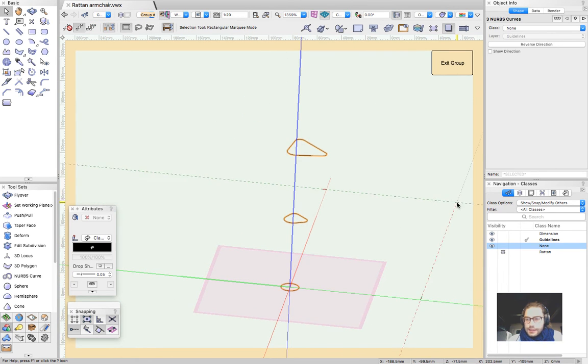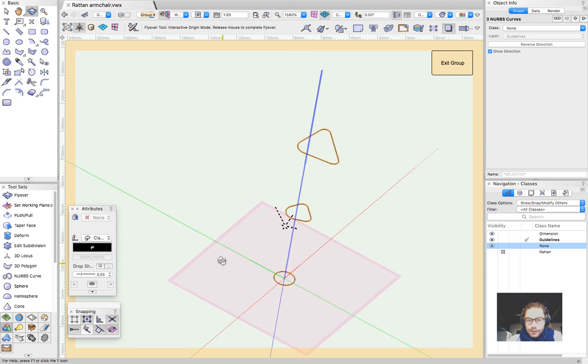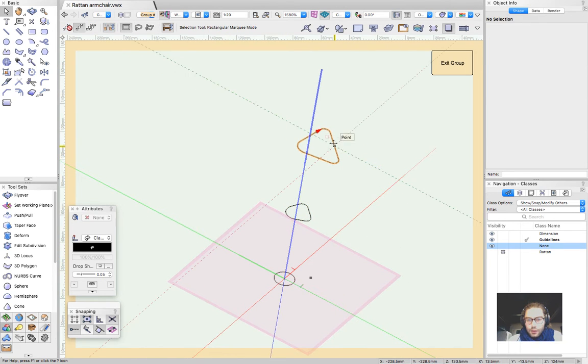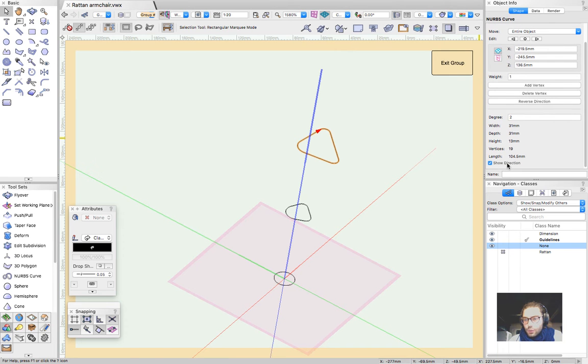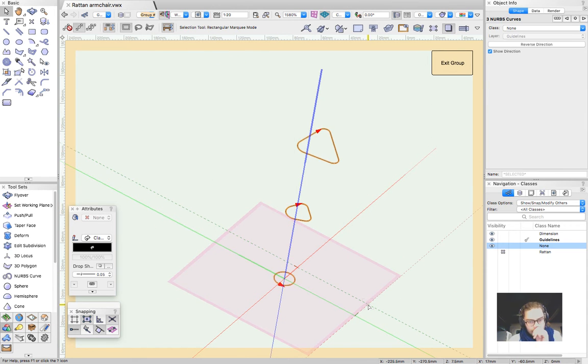Then the next step before we start creating the loft will be studying the direction. Every flat curve or 3D curve like NURBS has direction, and once you have placed a tick in the show direction box, you could study directions of all curves in the document.